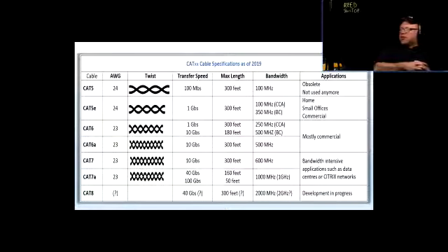I'm not going to get into the science of things because, frankly, I never thought about doing a scientific examination of that CCA copper-cladded aluminum. But I'm just going to say it's not pure copper. There's an aluminum part in it. It's not as good a conductor as pure copper. That's all. It's less expensive. Don't go for that. Just try to get the pure copper, and you're going to be fine. You're not going to get so many annoying service calls or things like that.